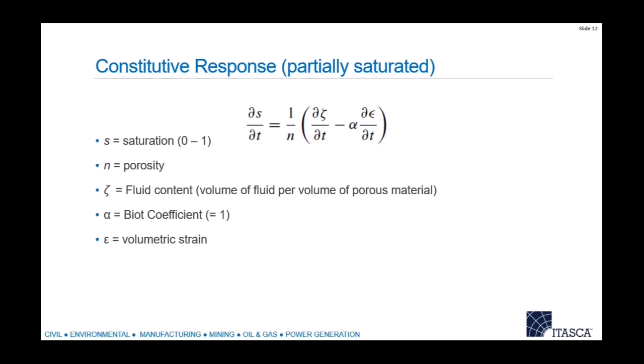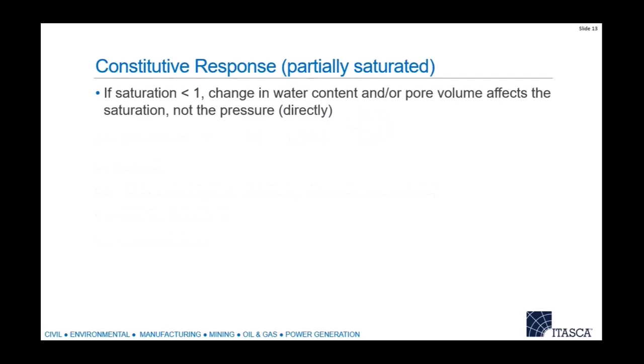So you can increase the saturation of the zone through mechanical volumetric changes. So again, change in water content and pore volume affects the saturation, not the pressure, at least until it fills up, and then pressure will start to build.